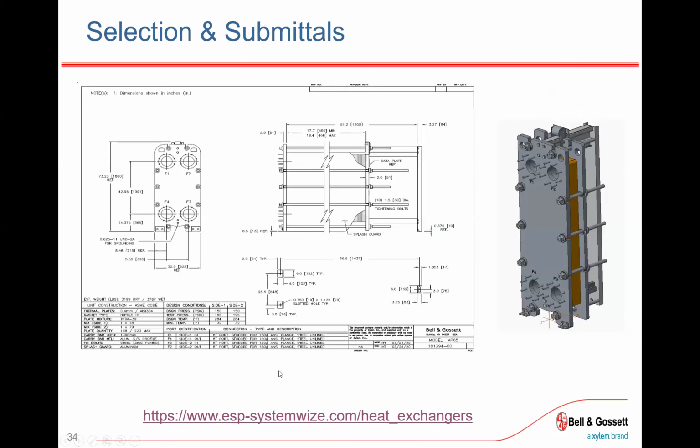Okay, so this is just a drawing that would be selected, but I'm going to jump into the sizing, so that I hope some of this will all come together. Actually, I'm going to go back here. When you go to ESP-systemwise or Bell and Gossett systemwise, it brings you to a sizing platform. I had the link set up so it goes directly to the heat exchanger page. So there are different tabs, pumps, and so on.